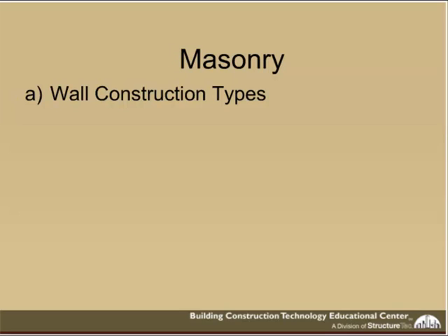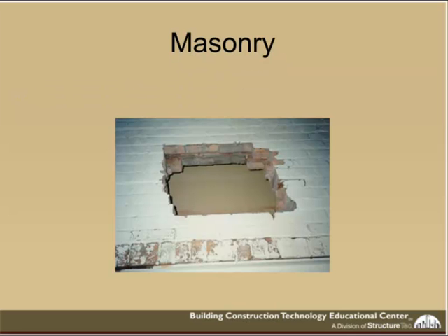Masonry comes in basically two primary types of construction. Mass construction and cavity walls are what people are most familiar with. Mass construction has been around since the time of the Egyptians and the Romans. The difficulty that it had was there was no reinforcement such as we have available now, so the weight of the construction required the walls to become much thicker as they became taller. Got an example here coming up of a type of mass construction. This is a two-wythe system, so there's two layers of brick there horizontally.